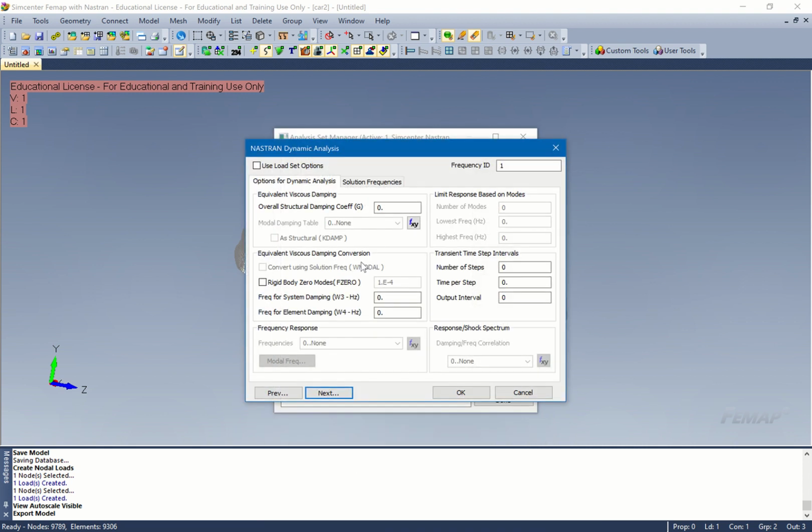And then, let's put the same damping in, but let's use 0.05. And then for the damping here, I can't remember the frequency, it used to say 20 hertz. Number of time steps, now this is interesting, because we definitely want to get a good profile on that displacement. But that's a lot of output, right? So what I want to do is run this thing for, let's see, how about 2 seconds? I think it's a lot. 1 second of data? See if we can do it.